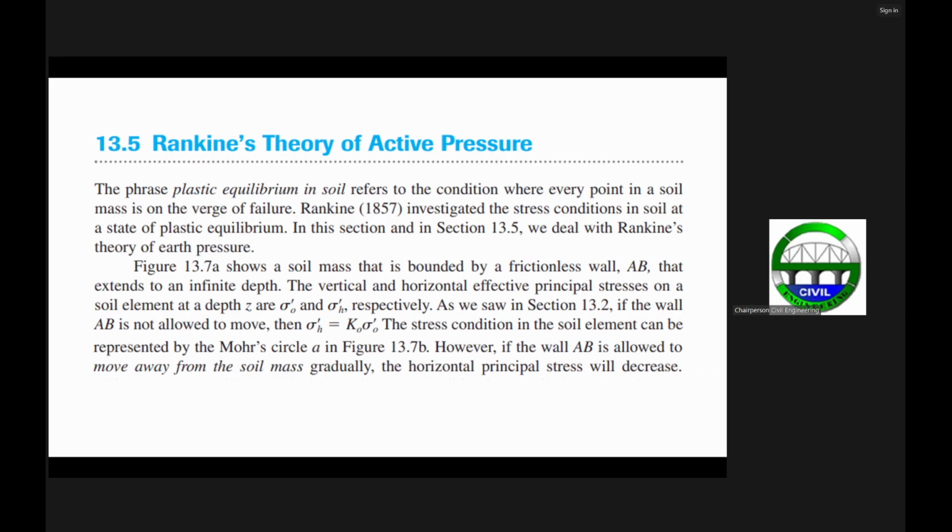For example, if you see that there is a need to do some backfilling works wherein you need to design a retaining wall, say less than 5 meters, maybe a concrete retaining wall is still okay. Then we can provide the earth pressure coefficient. So let us now talk about the active earth pressure, then later the passive earth pressure.